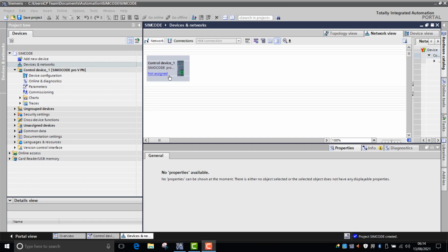Well, if you've experienced premature failures of key equipment within your facility, a power monitoring system can act as your crystal ball to clarify if your motors, pumps, whatever device it may be, are susceptible to premature failures. So if they fail earlier than predicted, you can investigate the possible causes. Normally things like harmonics can cause microjogging and motor vibrations in motor bearings, and other things like transients can cause cable insulation to heat and wear, resulting in short circuits.